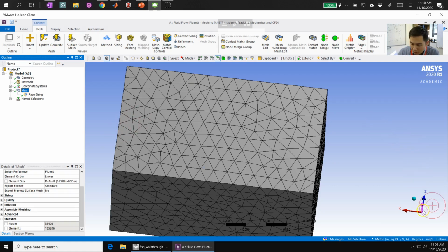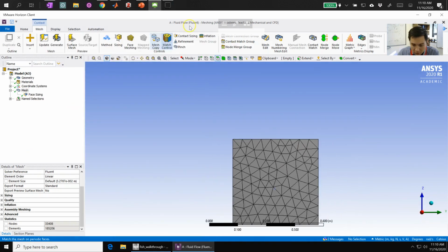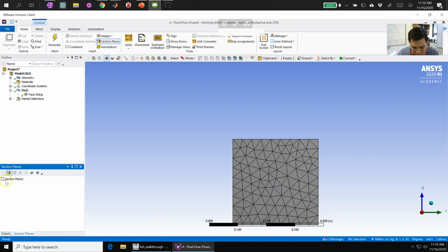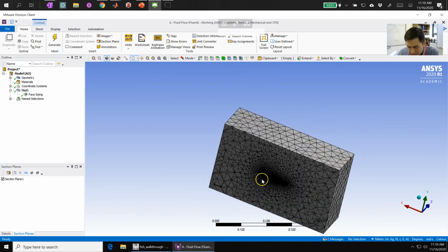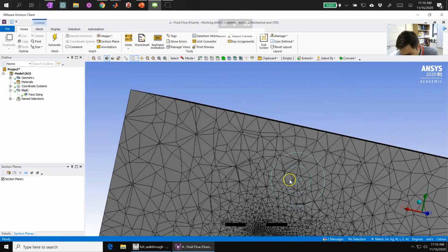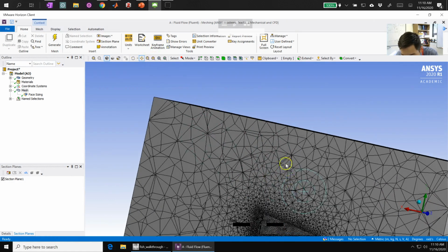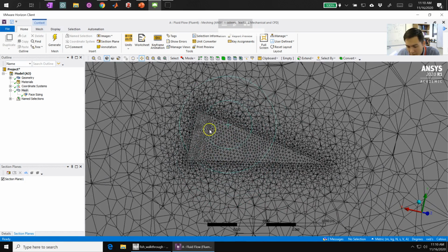we can get a better view of what that is going to look like if we turn back on our section view. Now we can zoom in a little bit on our wedge, and we can see that the wedge is pretty clearly having more elements on the surface. So this is a higher resolution. We have an idea of roughly what the boundary layer thickness could be. Fortunately, we're going to be operating at relatively slow speed, so the boundary layer thickness is going to be pretty significant.